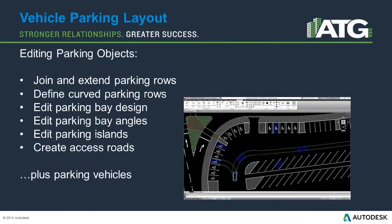Using AutoDrive, a vehicle can be selected from the vehicle library and placed within the drawing automatically and snapped into position. And by moving the cursor either to the end of the bay or something, you can define if the vehicle is parked forwards or backwards in the bay, and ensure the correct size for that bay, as well as being able to pull forward and make the turns and turn radiuses. For example, an F350 pickup truck won't fit inside just your normal parking bays.